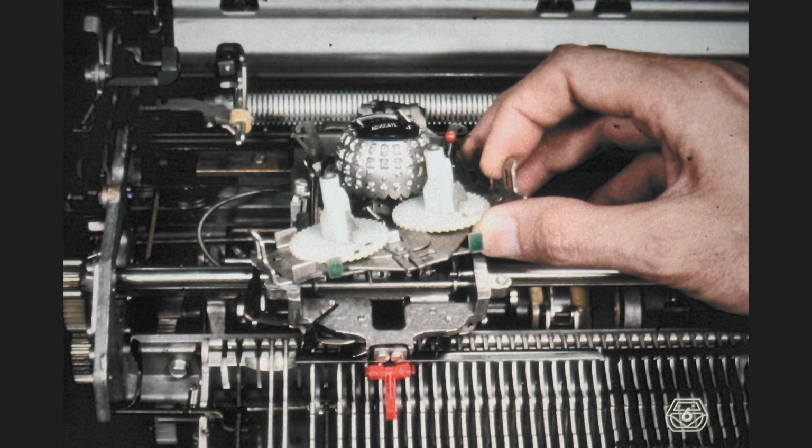Without forcing anything, rotate the loosened mechanism into the position shown here, right side to the rear as far as it will go, while at the same time lifting the front, in an effort to bring the ribbon feed cam follower, located under the ribbon mechanism bracket or plate, all the way to the front.